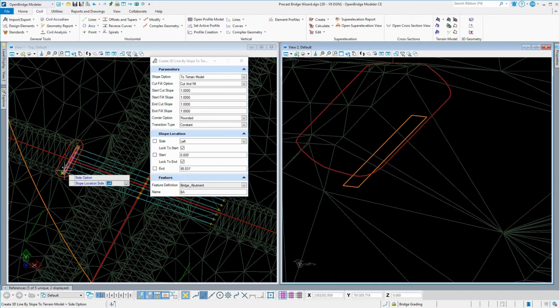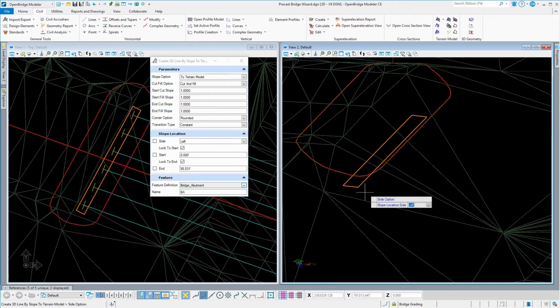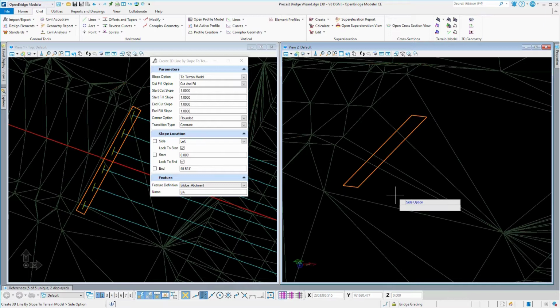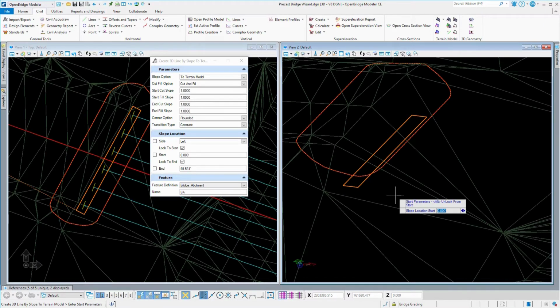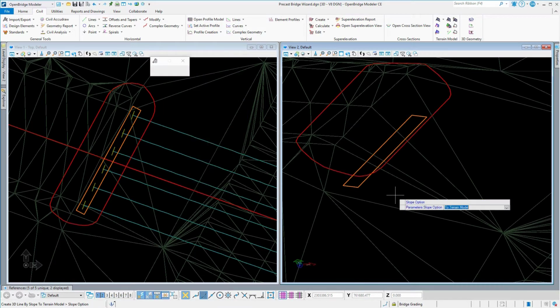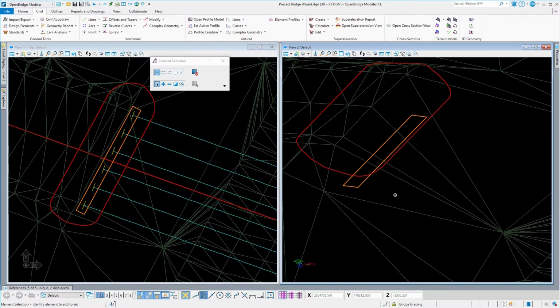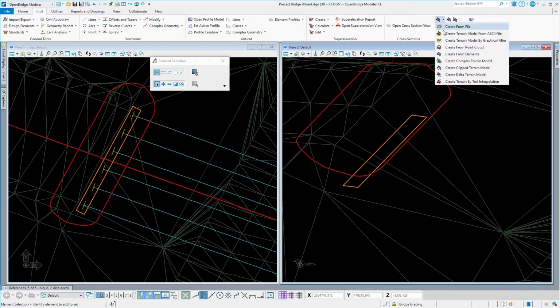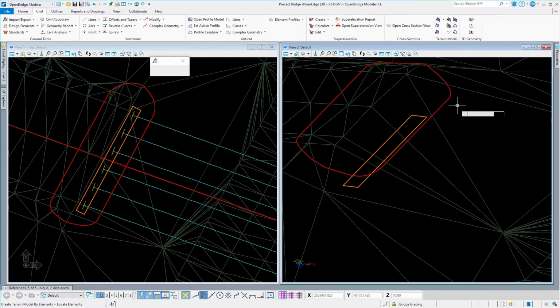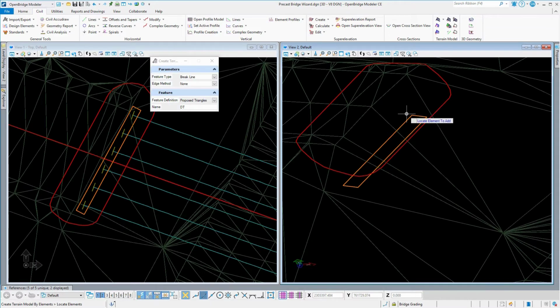So you can see we can specify the slopes, the direction of that excavation, and that's it. At this time, I will have basically two 3D lines, one at the bottom of the cap and one projected from that bottom of the cap at a certain slope matching the terrain. Then I will create a terrain, create from elements. So I'm going to make that bottom of the cap a terrain.